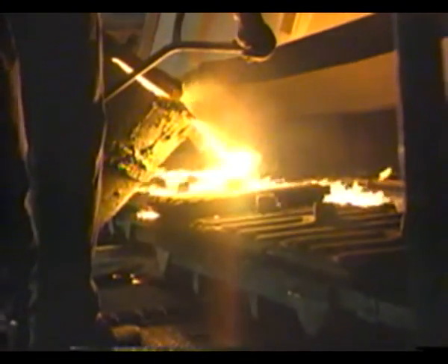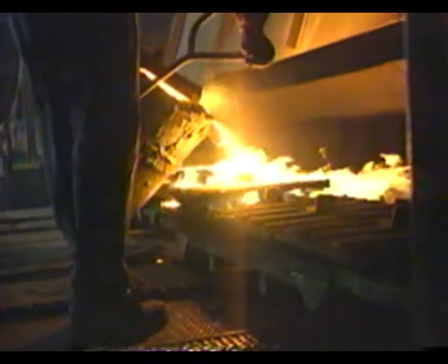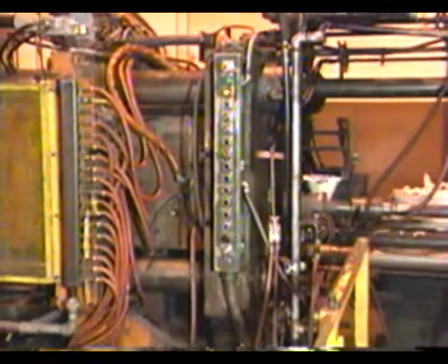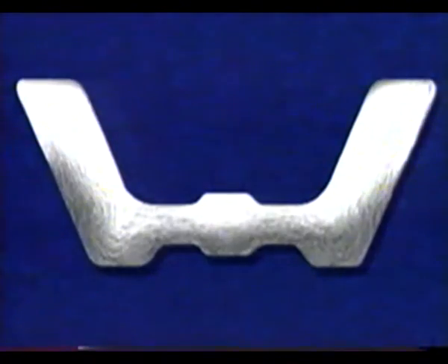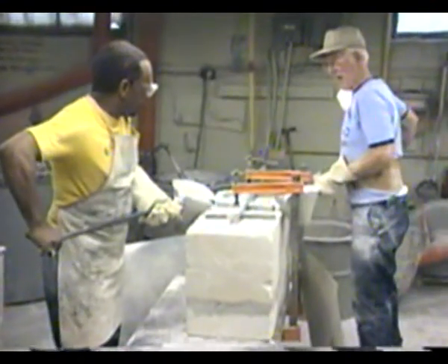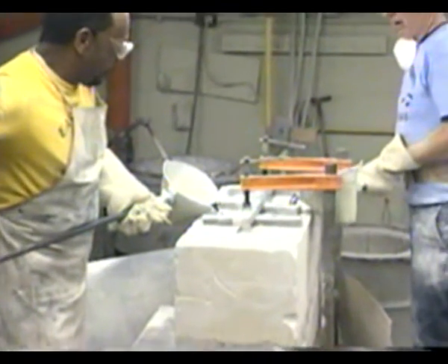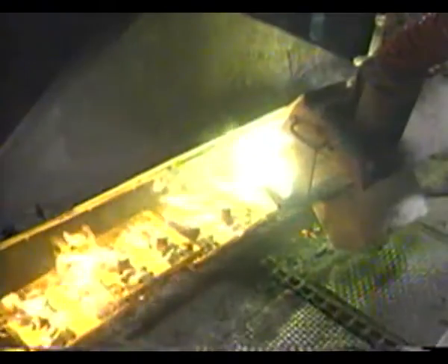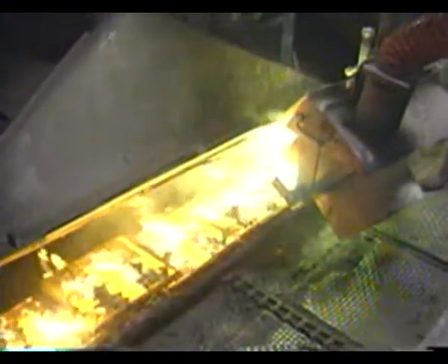Let's review the material contained in this videotape. Casting is the solidification of molten metal that is poured into a mold or injected into a die having a cavity in the shape of the desired part. Castings typically have an isotropic or uniform grain structure and properties rather than the directional grain structure and properties of wrought metals. Casting is usually the quickest way to shape metal into a part. Because of this, casting is used both for prototyping as well as production of large quantity parts.